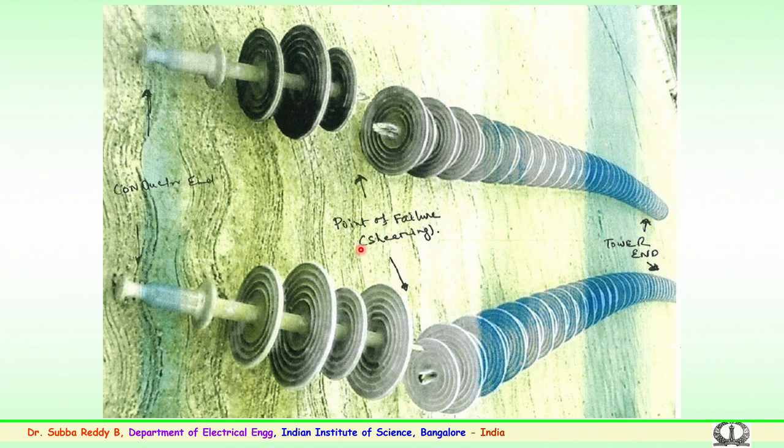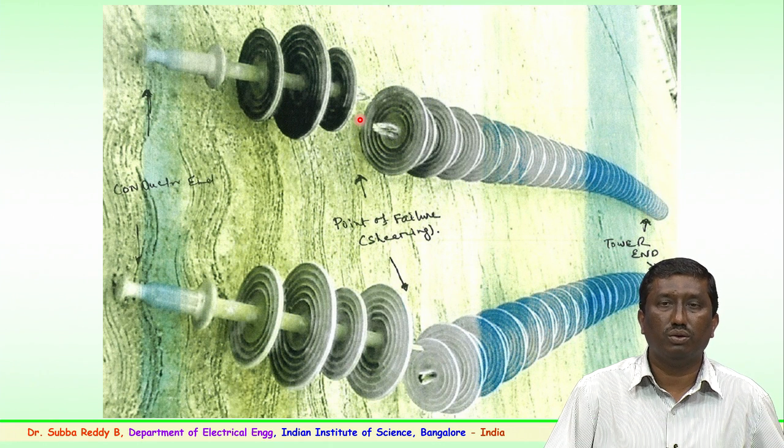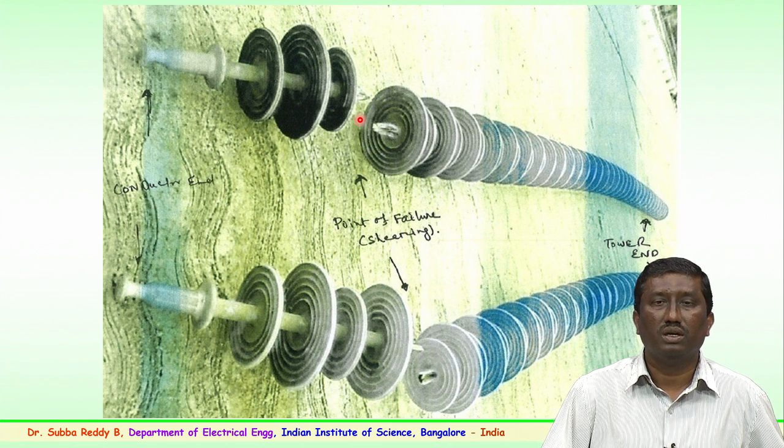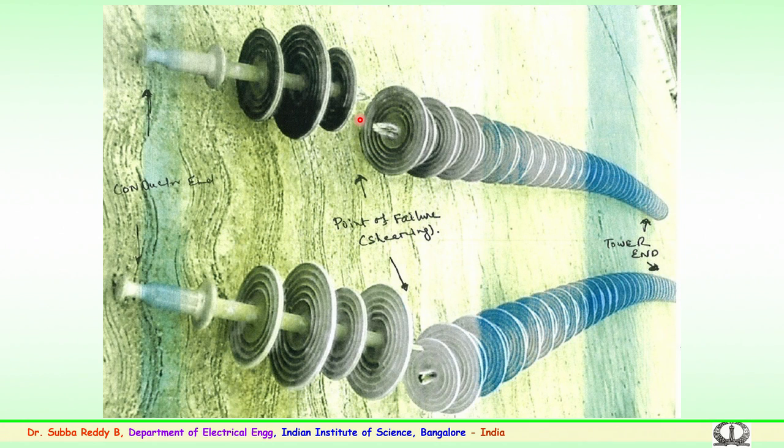So, these are again various failures which have been noticed over a period of time in polymer insulators. This is particularly for a transmission system, a 765 kV line, where the tower failure has happened 8 to 9 months after the erection. So, a very serious concern. The technology which you are adopting has to be carefully looked at, so that equal importance is given not only to the material and the newer technology, but to how it is being used, how it is being erected in the field, and the orientation of the corona control rings. This has led to the failure because of the placement, design and orientation of the corona control rings.